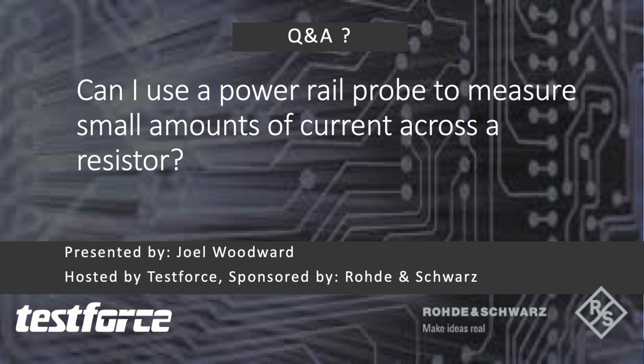Power rail probes that are in the market today are single-ended, so it would require that a shunt resistor at one end be connected to earth ground. The second consideration has to do with common mode rejection ratio. The probes are measuring very, very small amounts of noise and ripple, and if the DC value changes, it has a relationship on the probe's ability to see and accurately measure those very, very small signals. So the answer to that is, it depends.